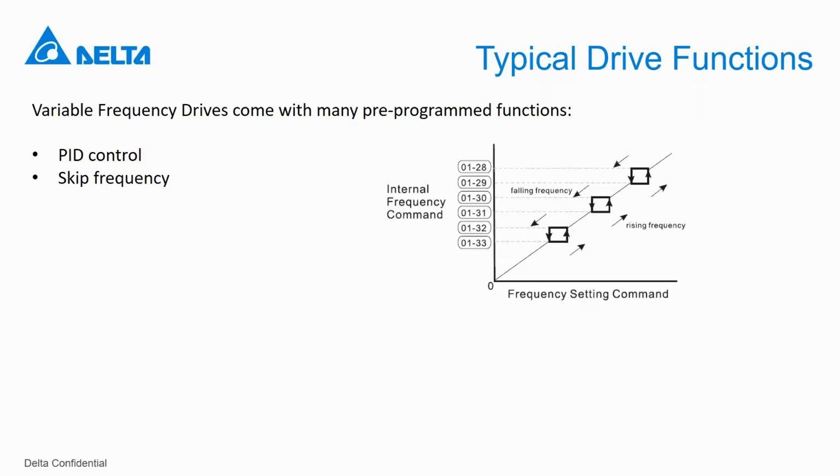I just mentioned an analog input of 0 to 10 volts, but you can also do it if your input is 4 to 20 milliamps. That would work in a similar manner. If your command is somewhere at 12 milliamps, then that can be 0 Hertz. When it's below 12 milliamps, it can increase the speed in the negative direction, in the reverse direction, and when it's above 12 milliamps, it can run in forward direction.